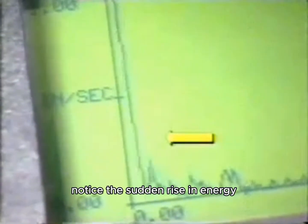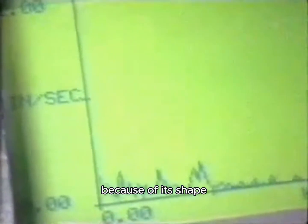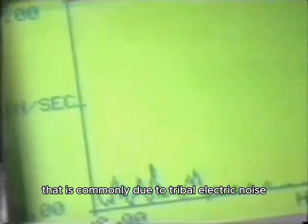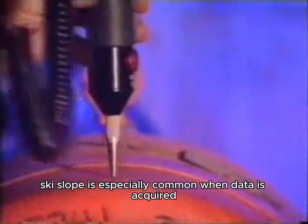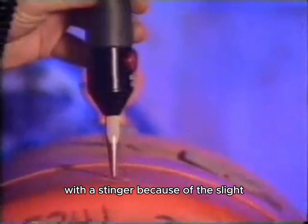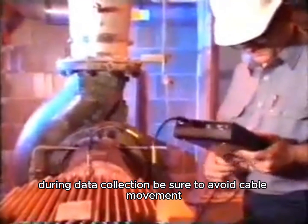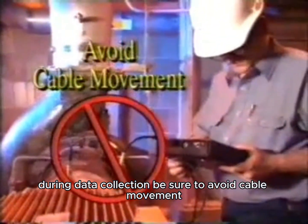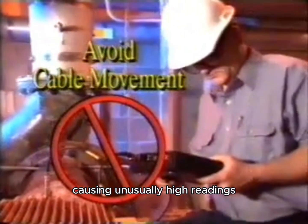Notice the sudden rise in energy at the low-frequency end of the spectrum. This is often referred to as a ski slope because of its shape, but is commonly due to triboelectric noise or cable movement. The ski slope is especially common when data is acquired with a stinger because of the slight continual movement of the hand and cable. During data collection, be sure to avoid cable movement, as that may add a ski slope to your data, causing unusually high readings.